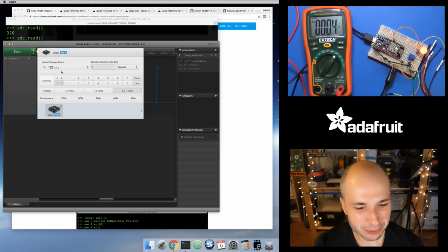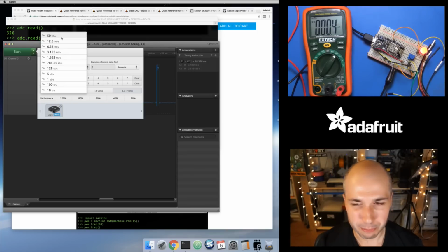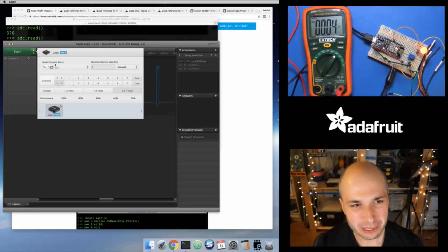of my cameras going into the same USB bus as this thing, and this is USB 3.0, and you can use a lot of bandwidth with 50 million samples per second when you turn on a bunch of channels. Generally you want to set your sample rate to whatever value makes sense, which usually means at least double your frequency. So at least 120 times a second.